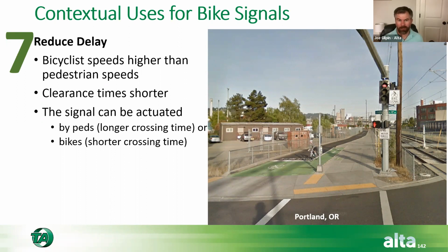So you get to these intersections and you have an actuated set of signals. If you were to use the pedestrian crossing, you would have to use pedestrian clearance times through the whole thing, so 3.5 feet per second across the entire wide intersection. What the agency decided to do here was, let's have bicyclists call a specific bicycle signal, let them leave the class 1, go into a bicycle area, and then we can shorten the amount of stoppage that happens for other people to get the bicyclists through safely.